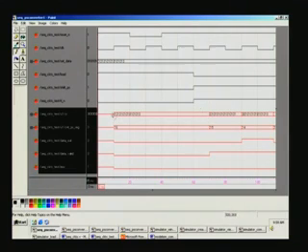There is also a counter which keeps track of the number of bits sent over the serial channel. We start with 16 here, and it starts decrementing every time a bit has been sent. The first bit being sent, 1010 becomes 010, which means it has been right shifted, and so the very first bit on the LSB will go out as data out, that is what you have here.